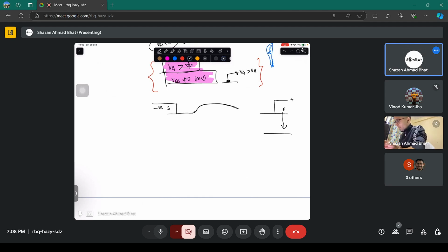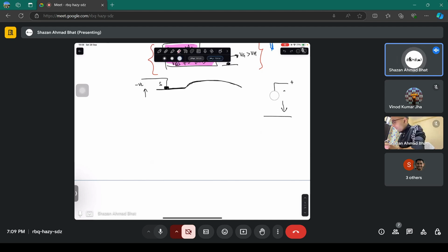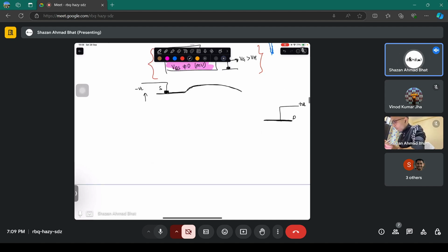Okay. इसका मतलब यह है कि जो सोर्स एंड भी है वो भी उसी अकॉर्डिंग ऊपर जाएगा because you are applying negative here. Negative will increase the electrostatic potential energy of electrons on the source side. So this will go higher. यहाँ पे जो बेंडिंग था वो ऐसे जाएगा या जो हिल बन रहा था, this hill will go like this, and because you have applied positive on the drain side this end will go down. So this is the drain side now, positive applied. Now you have to connect this region to this region. It looks something like this.